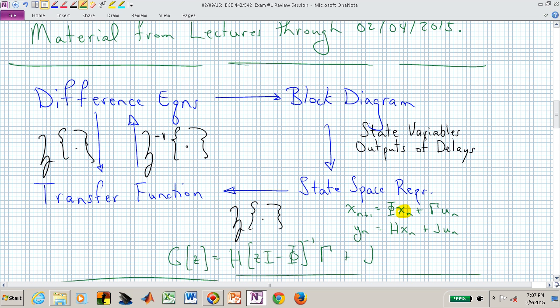Then we will, if we haven't already, tonight hopefully show that you can go from the state space representation to a transfer function by this matrix algebra. The output matrix H times this matrix zI, where I is the identity matrix that's the same dimension as the system matrix Phi. So if you had a 4 by 4 Phi matrix, I is a 4 by 4 identity matrix. Ones on the diagonal, and you're now scaling each of those by this complex variable z.